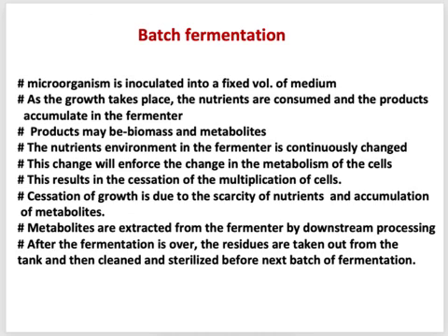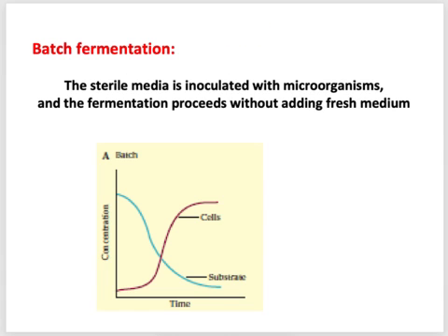So if you want to represent batch fermentation graphically, we can show it in this way. On the x-axis you put the time, on the y-axis the concentration. As the fermentation goes on, the concentration of substrate will go down, it will get reduced, and the concentration of cells will increase until their growth ceases.